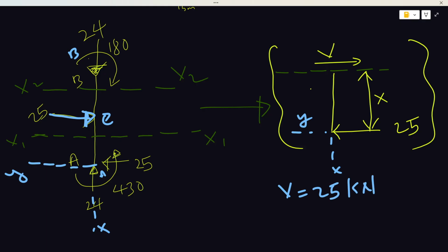In the video coming up on shear force and bending moment, you would understand why we are applying equilibrium equations to these free body diagrams. Ordinarily, you can go through another route, which is the normal one where people just bring V from nowhere and say, okay, since this 25 kilonewtons is coming up, maybe we're talking about VA, then at A it will be 25.